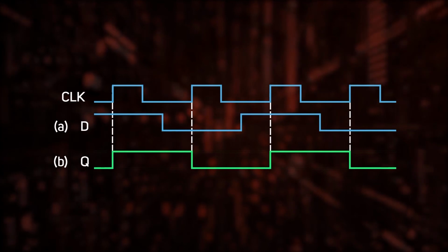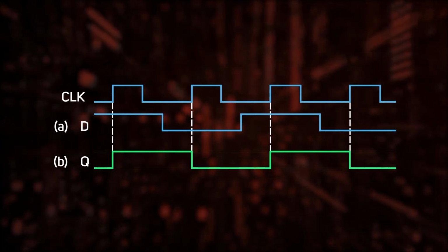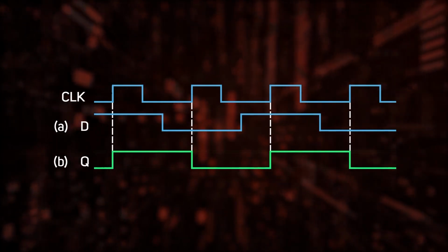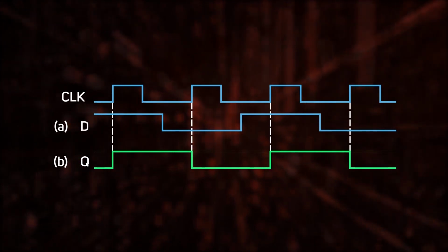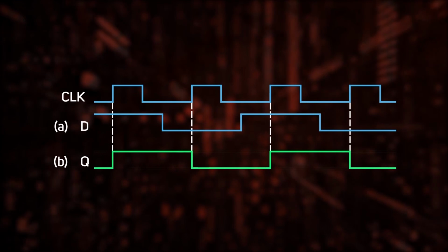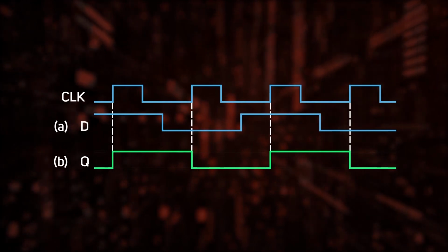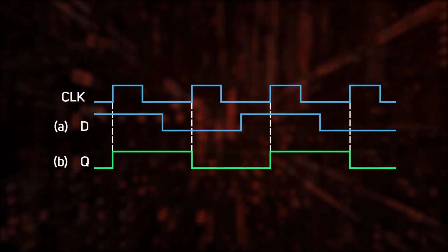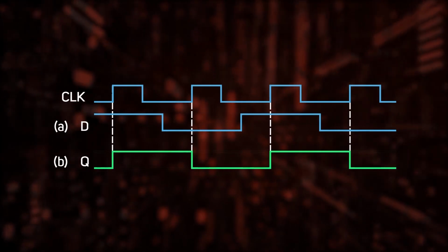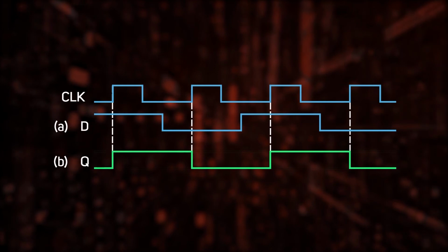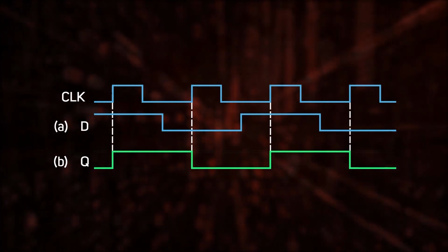Now, we are on the third rising edge. What is the value of D? It is high. Now, what should happen to Q? It should move to a higher level and it did. It remained in that state till the next rising edge. Here, D was 0 at that time and the output Q dipped to 0 and will continue to remain the same till the next rising edge.